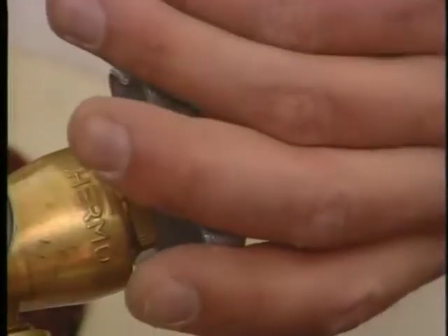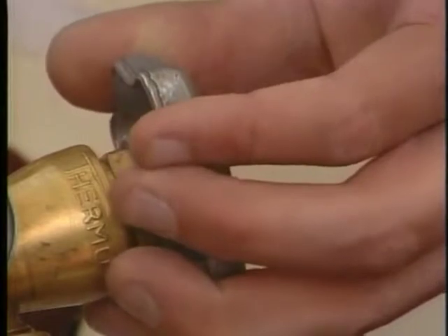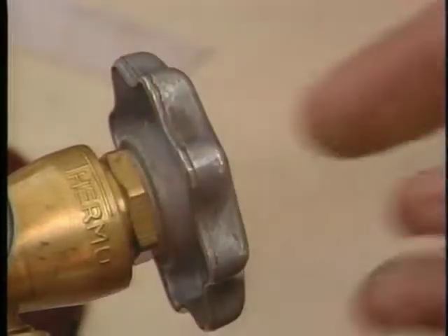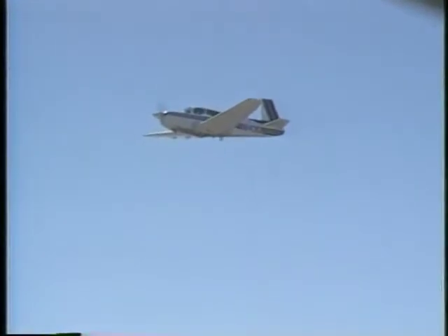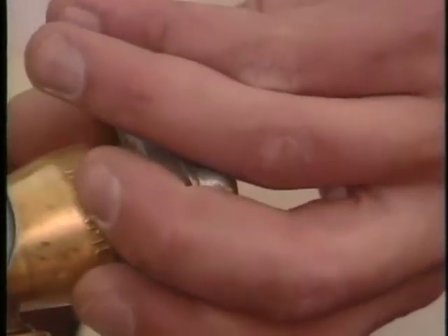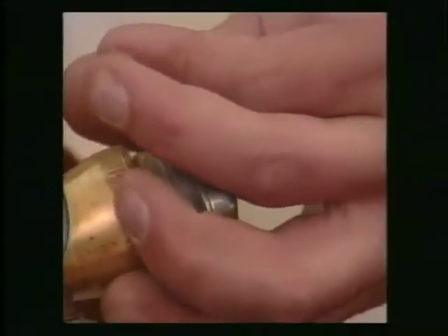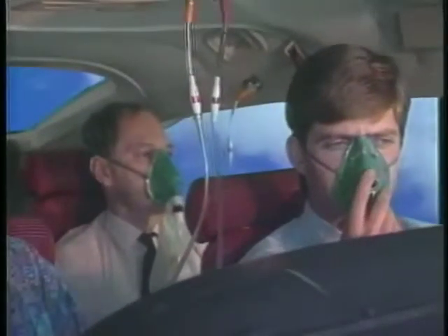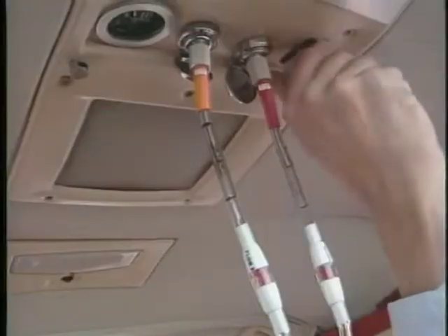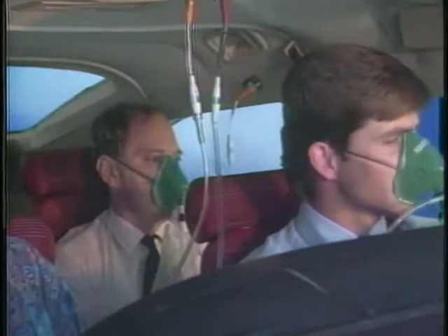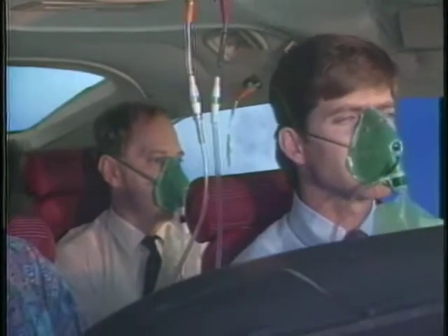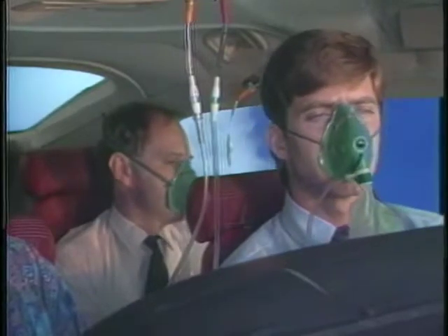A manual regulator works the same as a water faucet. Opening the valve increases flow. The disadvantage of a manual regulator is that you must readjust it as you're changing altitude. With an automatic regulator, all you have to do is activate the system with the on-off valve. The system then compares the atmospheric pressure and cylinder pressure and adjusts the flow accordingly.